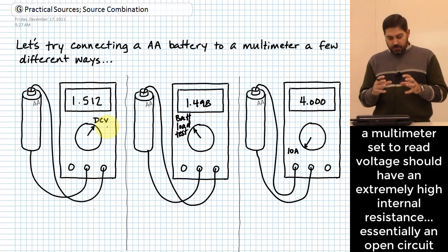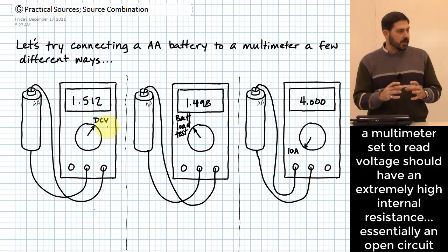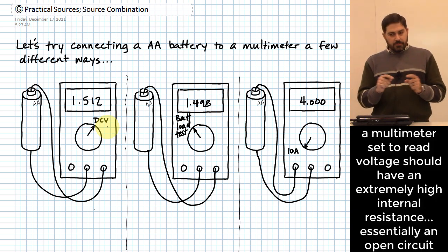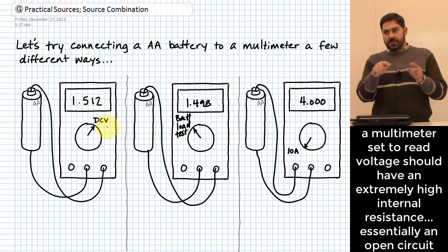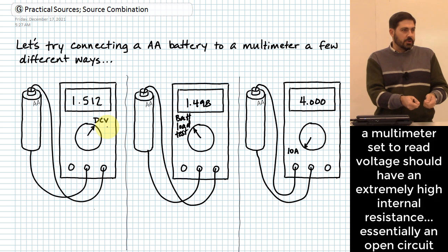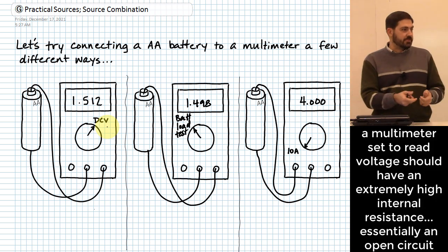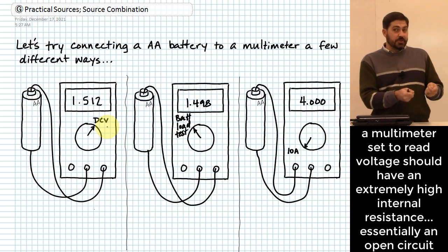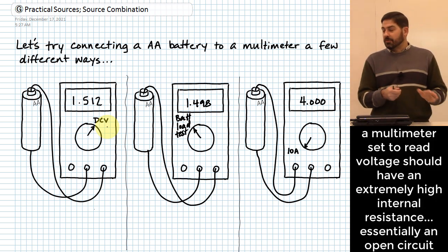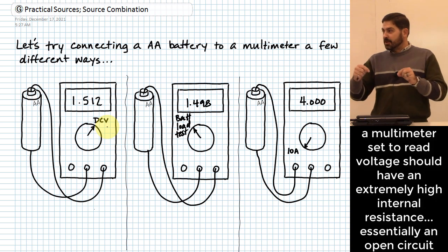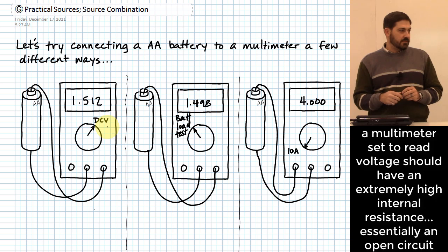Let's say you're doing some tests on a little circuit network and you have some fairly large values of resistor that are in this little resistance network, and you take your meter and you try to test voltage across one of your resistors in the network. What happens if the meter is anything other than a really, really large resistance value? Well, what it'll do is the multimeter itself will start becoming another resistor in the circuit, and it will change the value that you are trying to read.